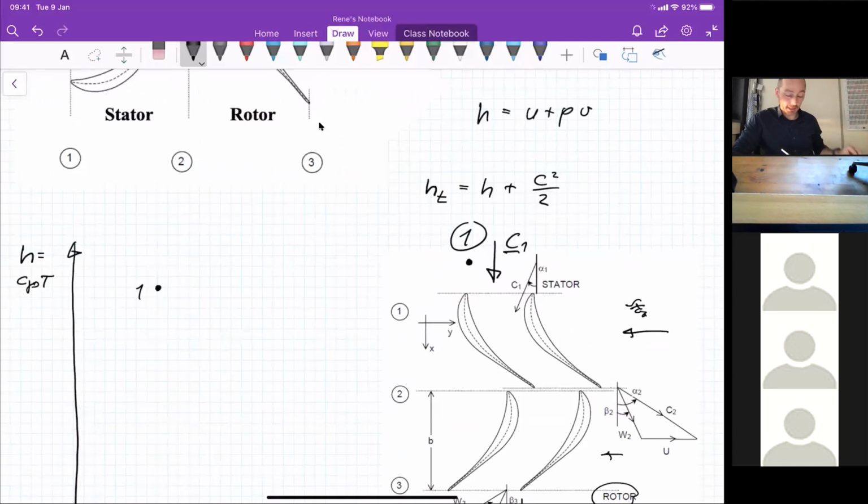No, it's because this enthalpy will show up in many definitions, in 2 definitions mainly, which is the definition of how much heat do I need to add to a closed system when I keep the pressure constant, which gives me my Cp value, and Cp is nothing else than the partial derivative of enthalpy with temperature along constant pressure.